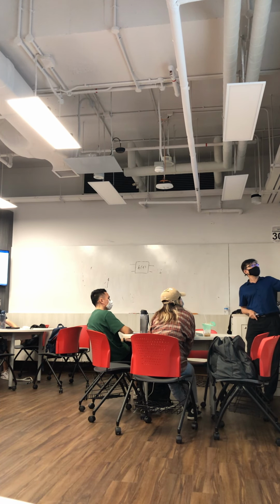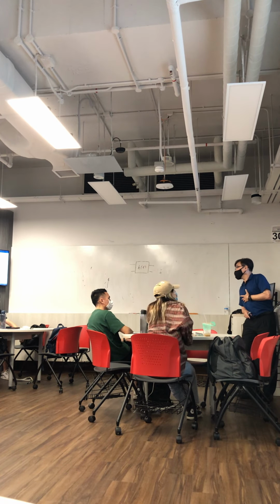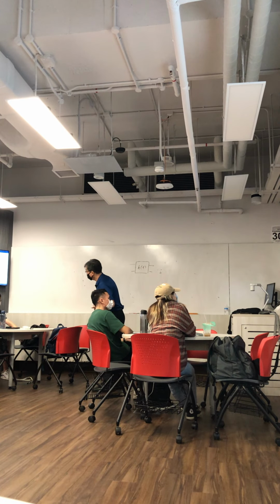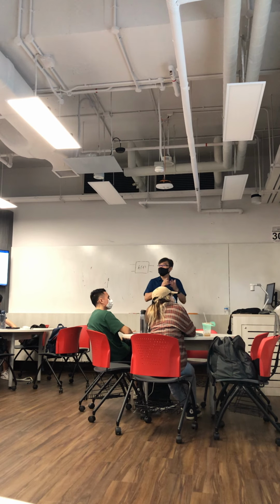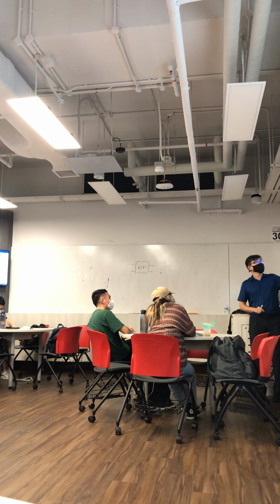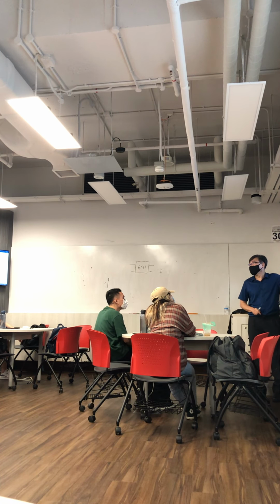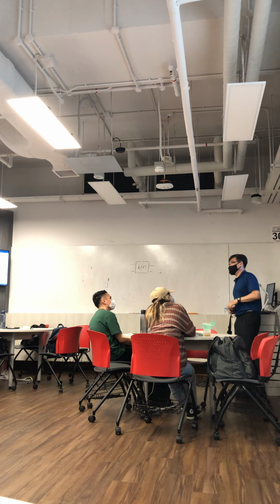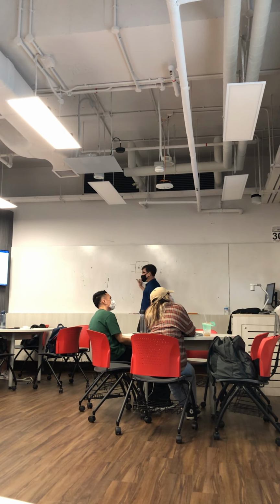So if you apply the Laplace transform, the impedance of a capacitor is actually the voltage across the capacitor in the time domain divided by the current through the capacitor in the time domain, right? Then you apply the Laplace transform to the voltage, and the Laplace transform of I is equal to this. Now you can see I can change this to sC, and dV by dt becomes the Laplace transform of V. So these two cancel, and I get 1 over sC. That's the reason why the impedance of the capacitor after Laplace transform is 1 over sC.